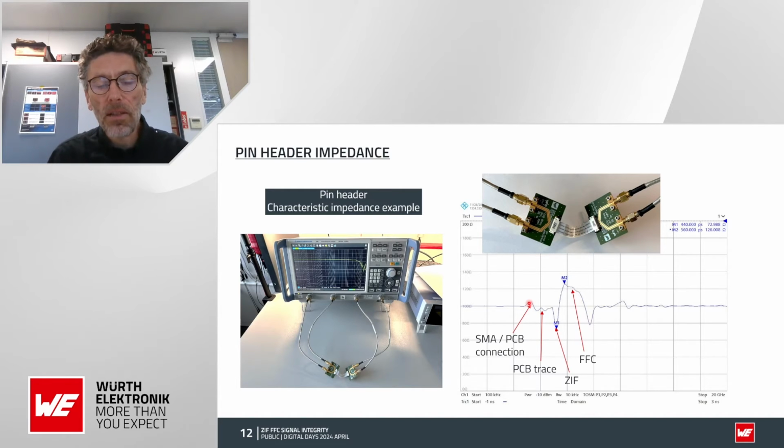These are good connectors, but it is not possible to have strictly no impedance mismatch here, simply because you are in a perfect round coax, and here you go into a more 2D, two-dimensional medium. So you have a change in the geometry, so in the capacitance, so in the characteristic impedance.